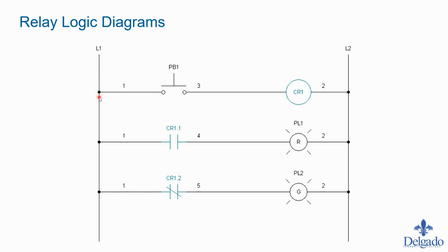So this again is our line side. This would be the black wire, if you're used to how things are wired in your house. We'll consider this the black wire, and this is the white wire. So the line and the neutral. And we know we don't ever touch the two wires together, because that will cause a short. But in this case, we're flowing our line side down this rail, and then we're tapping off the rail in multiple places to go through the rungs. We look at it as flowing rung 1, 2, 3.